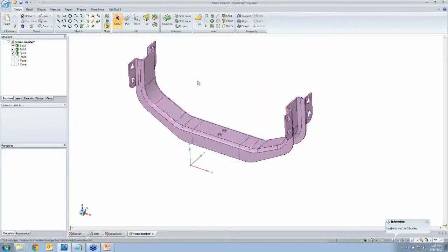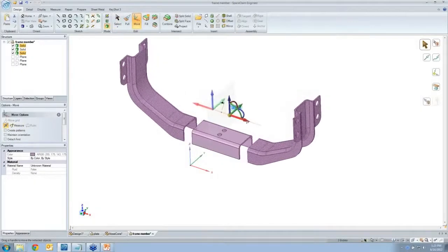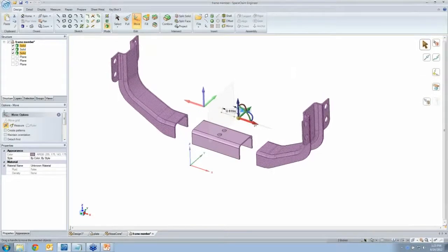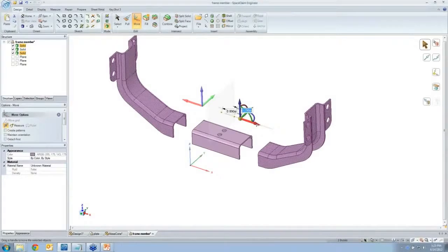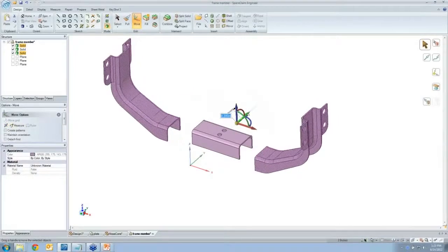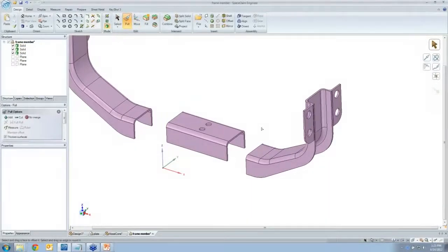Well, in order to get rid of this interference, I might need to take the 2 ends that are highlighted right now and shift them apart. I could move those in a symmetric fashion, so it just saves me a step basically. So I move them in a symmetric fashion, as far as I want, and again I can put precision in and say let's go exactly 0.35 inches, and then move them slightly this way, and that'll take care of the interference and where things now need to be situated.